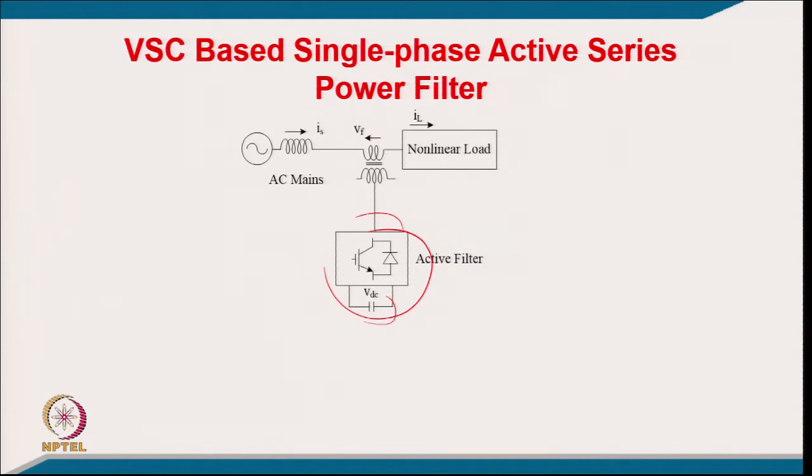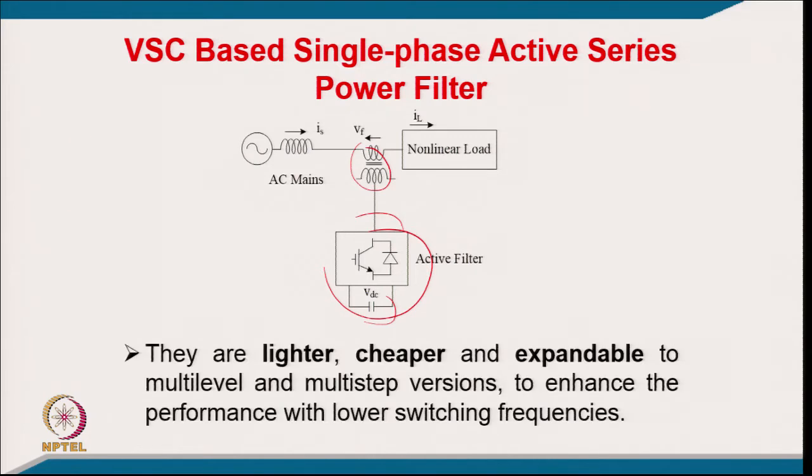And then you do not need any element on the AC side, but of course, there also you need the injection transformer. So, here also we have an injection transformer. Maybe in single phase we do not need one sometimes for a small rating, but an injection transformer is used for injecting this voltage. Compared to the shunt filter, it has more applications, not only voltage based compensation, but in voltage fed kind of load it also eliminates the current harmonics, will come with the example. So, it is considered more versatile.